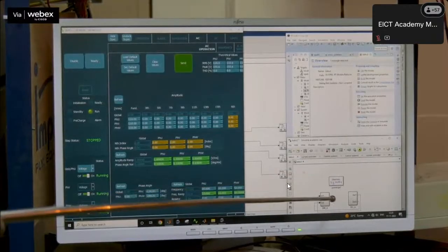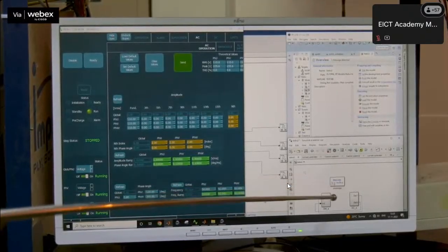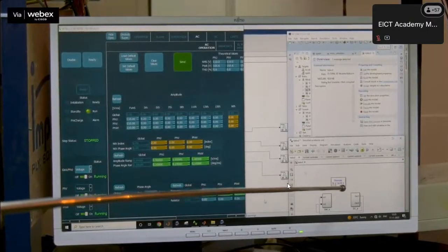This DC microgrid is initially simulated in MATLAB. Now, the simulated DC microgrid is rearranged in the form of a master subsystem and a console subsystem. The master subsystem consists of power sources and control or computational algorithms. At the same time, the console subsystem consists of variables that need to be varied during operation.